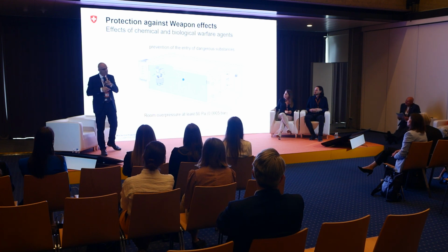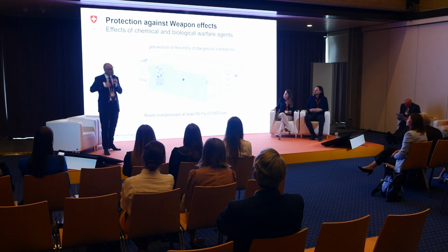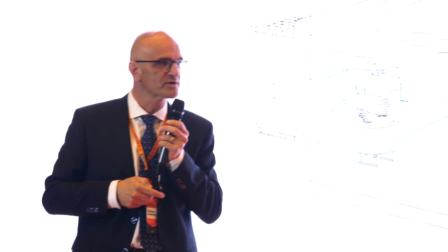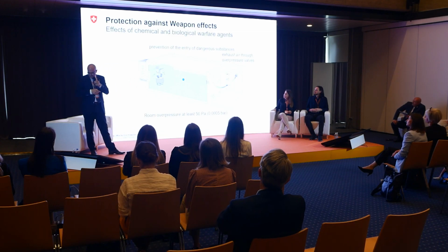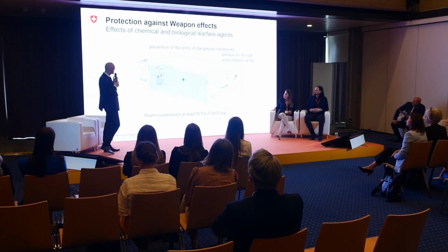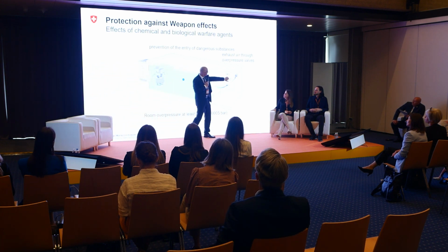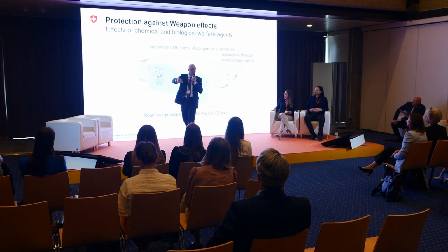You have overpressure in the system then. You can work it by hand, you can work it electrically, so it's absolutely proof for any event. In the end, you can work it by hand if nothing else works. And you have the exhaust air through the overpressure valve, and then when a bomb attack comes, the valve closes itself, so that you don't have the overpressure in there from the blast. And again, you have the exhaust gas there. So it's absolutely tight against influx of any gases.